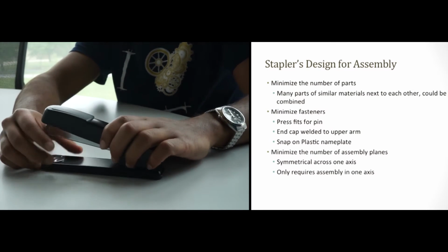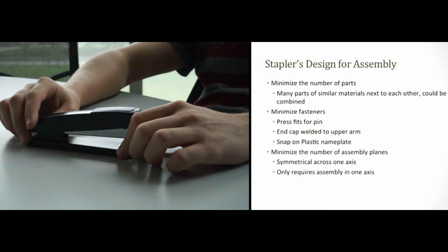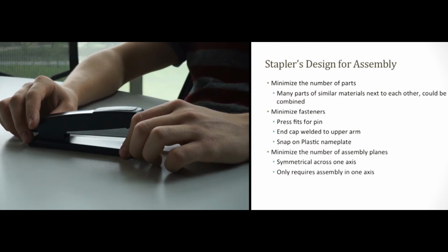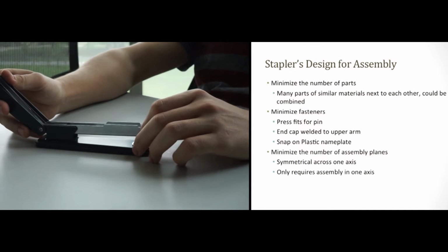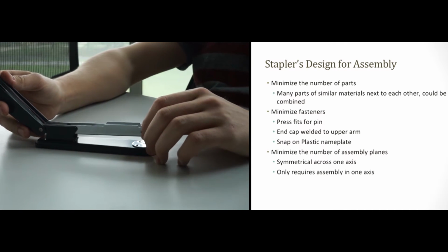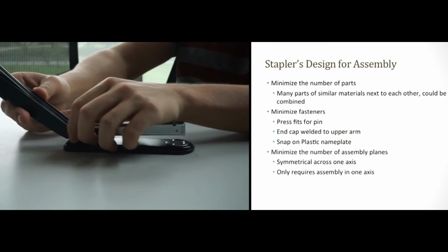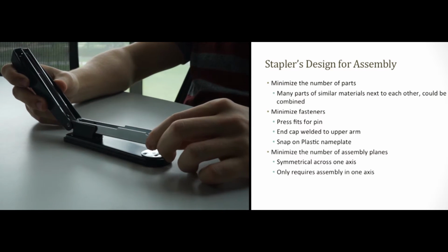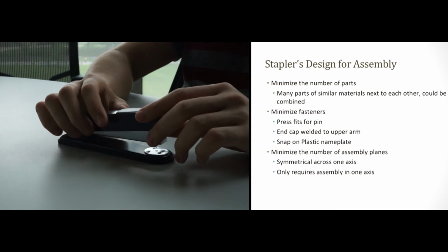There are several principles of design for assembly that we will address with respect to the design of the stapler. Firstly, minimizing the number of parts. There aren't many parts in this design, but there are several adjacent parts of similar materials that could be combined. Secondly, another element of design for assembly is minimizing the number of fasteners. This design utilizes press fits for the pivot pin, welding to attach the end cap to the upper arm, and a snap-on plastic nameplate. All of these attachment mechanisms minimize the use of fasteners.